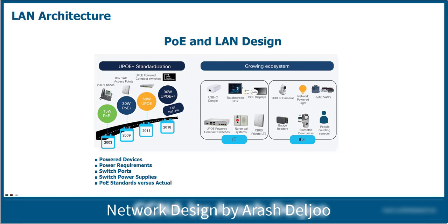After that, you need to think about the power requirement. You know that, for example, we have one PD device, and also maybe we have 10 PD devices. You need to sum and add the total PoE requirement of those devices together, and with this sum, you can find the power budget that you need in one device. Let me talk about that.